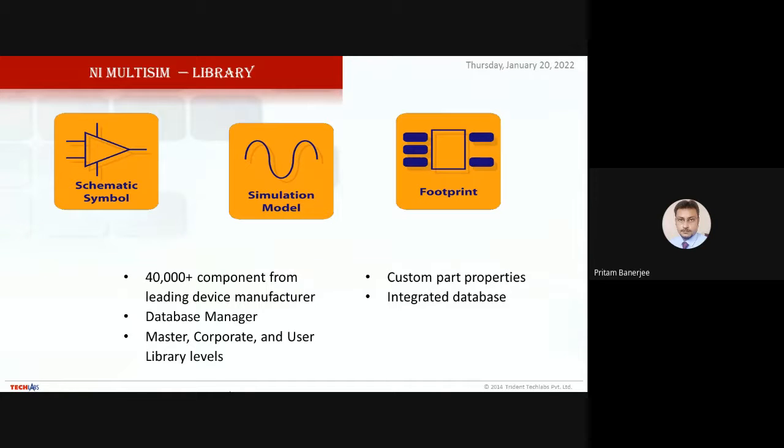And whenever you try to convert that circuit into a PCB design, that specific real component might be required, because whenever we go to the market and purchase any kind of component, suppose a simple diode, we don't say "give me a diode"; we need to specify which diode we want. Like 1N4007 from a specific manufacturer. It has all those details in the library,